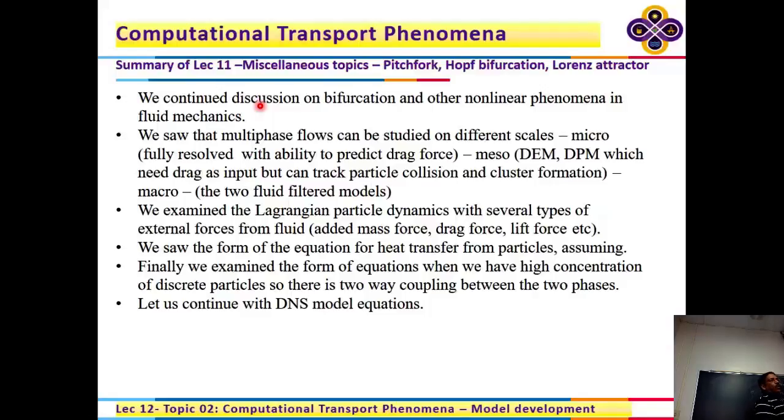You integrate that twice and you get that solution: v theta equals Ar plus B over r. So COMSOL has to solve only this equation. This is why the pressure doesn't influence the velocity. You get the correct velocity field when COMSOL solves for that, even though the pressure field is, you're saying, totally wrong, and I don't understand why that is. We need to figure that out still.